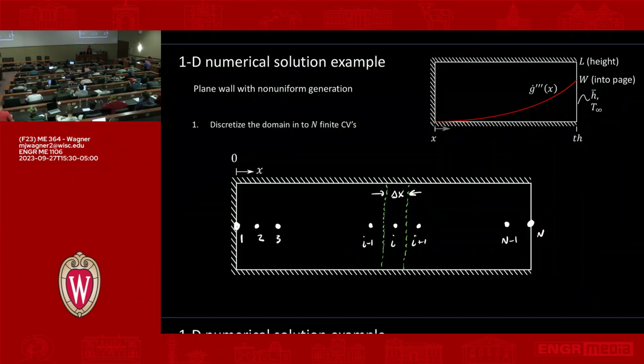What else here? So we have the control volume. I guess we could maybe write equations for this. So delta x, that length is equal to the total thickness. Let's see, what do we have? This here is thickness, right? That's the total length of this domain. So it's thickness divided by the number of divisions or number of control volumes. Well, we have nodes on the end, so it actually ends up being thickness over n minus 1. Right? That's the number of control volumes that we have.